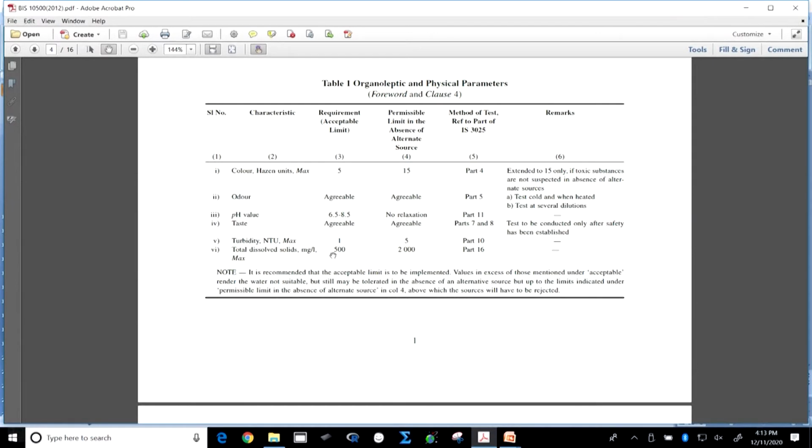In general, the required or acceptable limit is 500, but 300 or 350 is what is fine, or 300 milligram per liter. Above that, you will start to feel some discomfort, depending on where you have been living and how long you have been consuming that water.